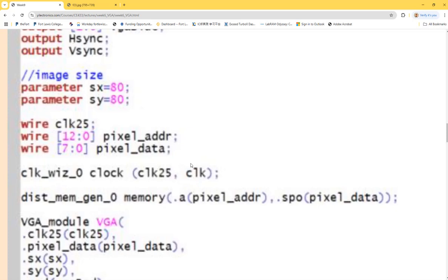So you can see clock 25 has to be the output, and clock is the input. Within the submodule, it's also declaring output first and then input. So they're aligned. But you can also use a dot statement to make the connections. It's going to do the same job.